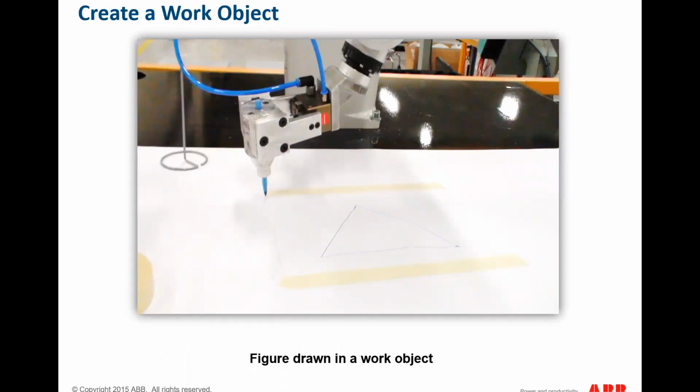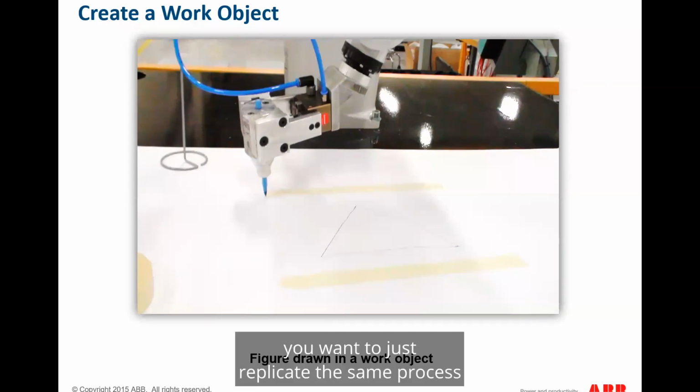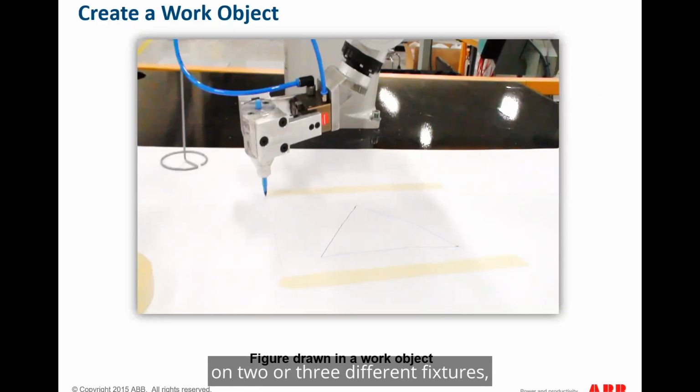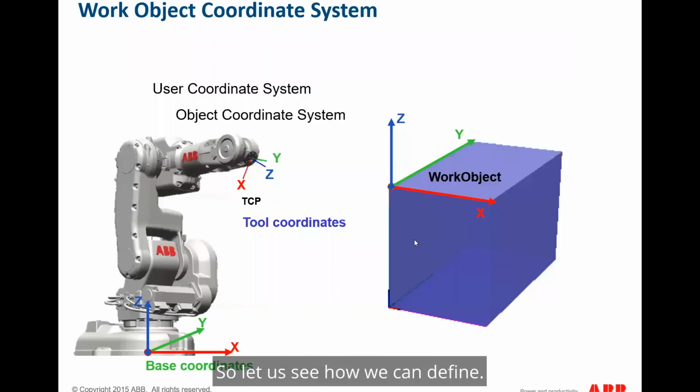previous lecture, the work object is specific to the work platform that you have for each product. So now, let us suppose you want to do the same work, you want to just replicate the same process on 2 or 3 different fixtures. Then we can assign a work object to each of these fixtures, and then we can run the same program on these. So let us see how we can define.